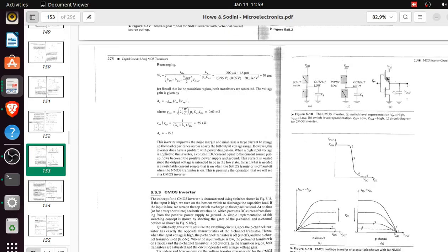So you can recognize a PMOS device, an NMOS device, and an output capacitance here. For some CMOS inverters, you may not see this output capacitor, but why it's there is to model the expected load of the CMOS inverter. Usually a CMOS inverter is going to be in a digital circuit, so at the output may be another CMOS device.